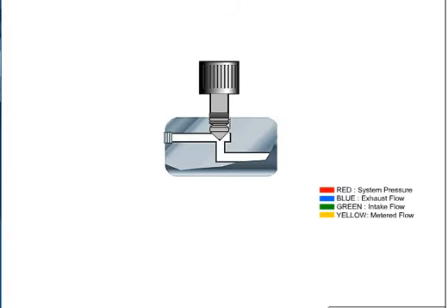The function of the flow control valve is to reduce the rate of flow in its leg of the circuit. Flow reduction will result in speed reduction at the actuator. A flow control valve builds added resistance to the circuit, increasing pressure, resulting in a partial bypassing of fluid over the relief valve, or a de-stroking pressure of a compensated pump. This reduces flow downstream of the flow control valve.